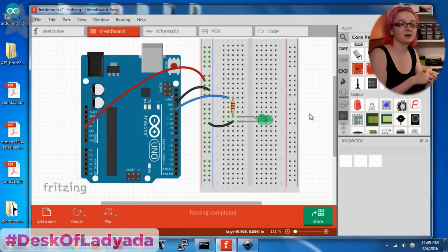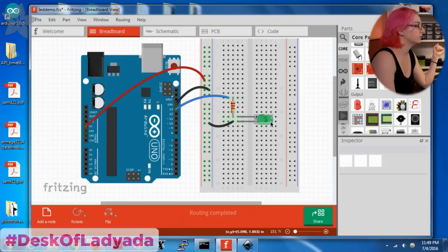Like with EagleCAD, it's very easy because it's just very mechanical. You just have to measure all the pads out. You're basing it off of a data sheet. The data sheet tells you the part's 3 by 3 millimeters, it has 0.5 millimeter pitch, and these are the size of the pads. It's very straightforward, like a bunch of rectangles, very easy. As you can tell, drawing an LED or drawing this Arduino is a lot more complicated.